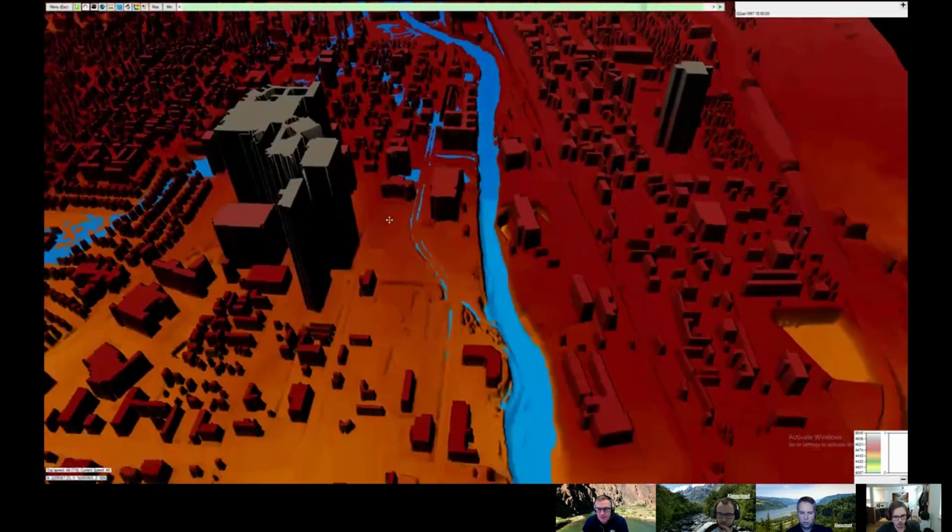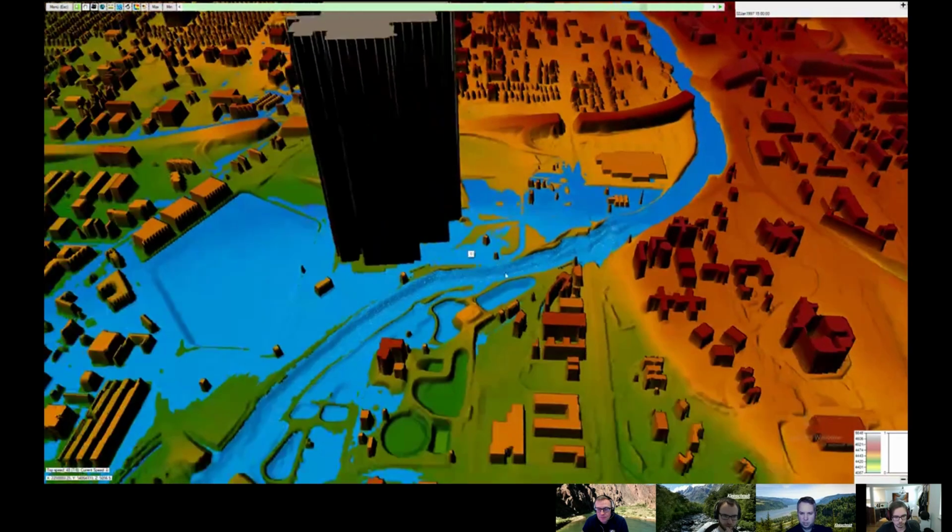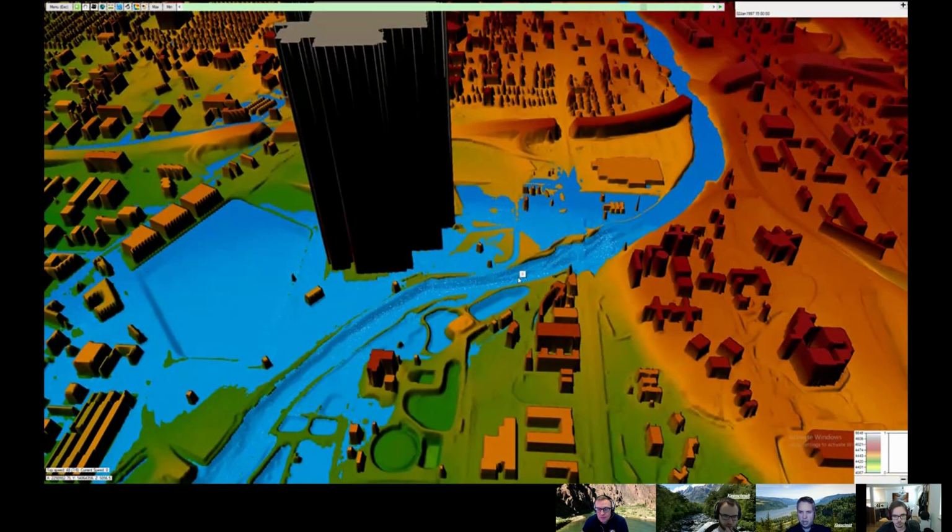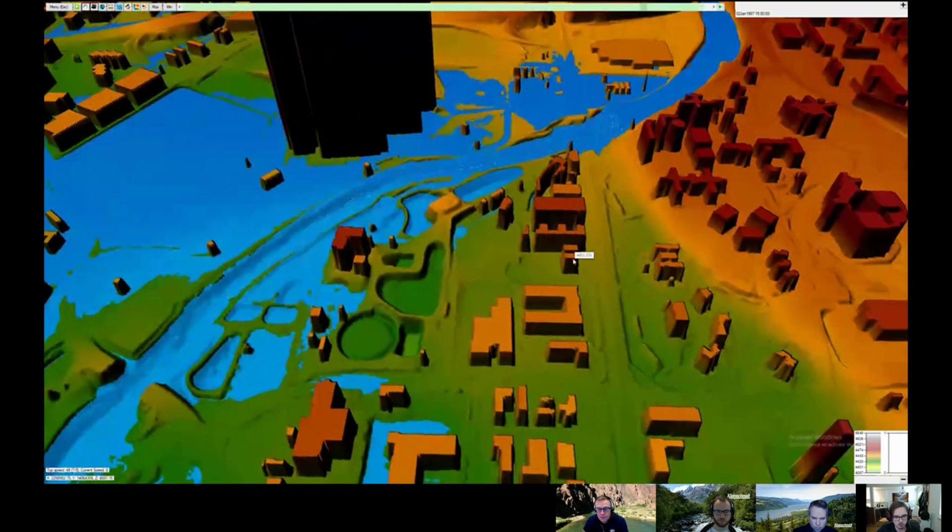And again, if you wanted to show the flooding at some specific location here, you could pause here and you could animate it. And you'd see the water come in and rise and go into the city area and then come back into the channel, right? Yeah, we'll get to that with flight paths. This is just all manual control. If you're confident about controlling, you don't need a flight path, or you're just showing a colleague. It doesn't have to be a formal presentation. Just to show what kind of maps you can do in the 3D viewer.